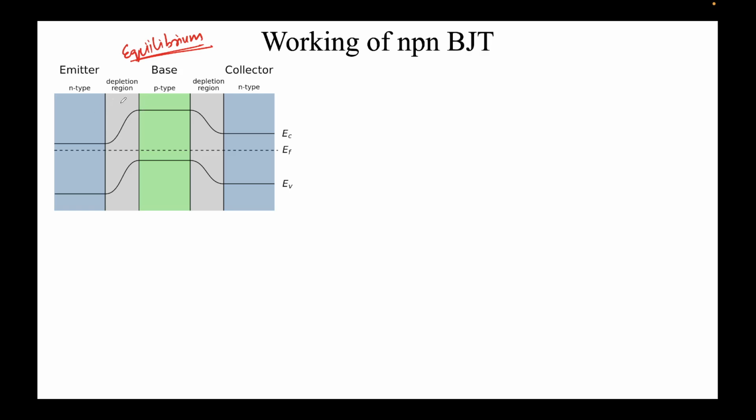As you know, let's just focus only on the emitter-base, only on the left side, this region. You'll obviously form a depletion region, right? And since this is N plus P, I'll write it as such. This is N plus P type. So most of the depletion region will be on the P type.